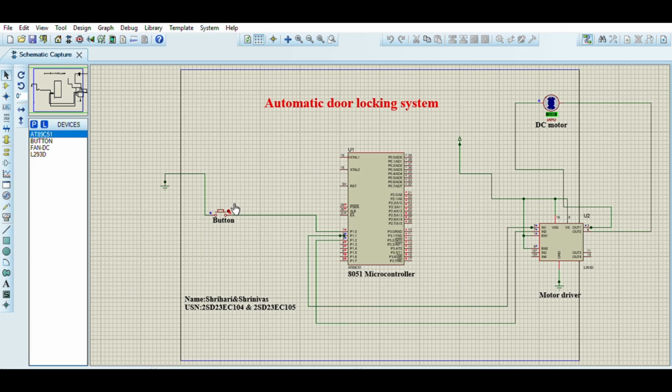On the button. The DC motor starts rotating clockwise. This means that relay 1 equals 1, relay 2 equals 0. If the motor rotates clockwise, the door opens. After some delay of time, close the button, the DC motor slowly stops and then rotates anti-clockwise. This means that the door is closed.